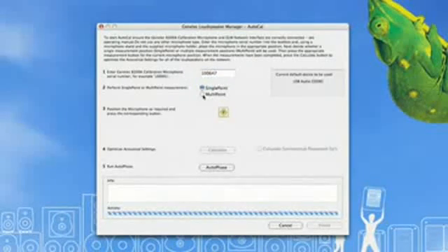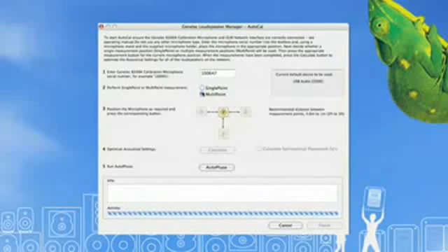For the measurement, there are two possibilities, a single point or a multi-point measurement. The single point method takes a measurement only at the primary listening position, whilst the multi-point method can average measurements at a maximum of 4 positions. Using multi-point measurements can be beneficial if you have to move around a lot while working, or if you work from different positions around your console or desk.